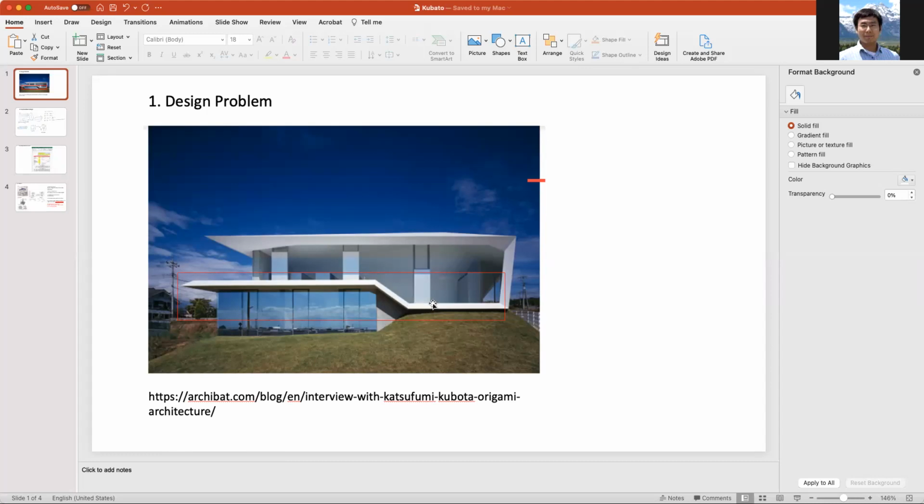Simply because we want to make a slender or thinner section, right? Imagine if I have to make a bulky section that can take care of the weight of the building and the live load, distribute the load on top of the building, it's going to be disastrous, right? And you notice that there are only very few columns sticking through this, and this glass cladding does not take any load, right?